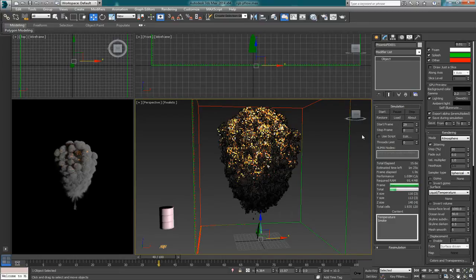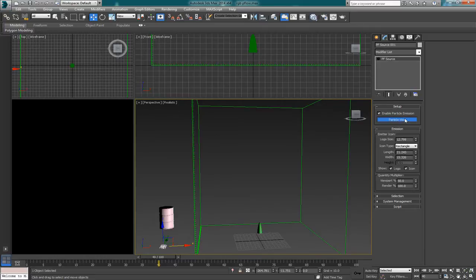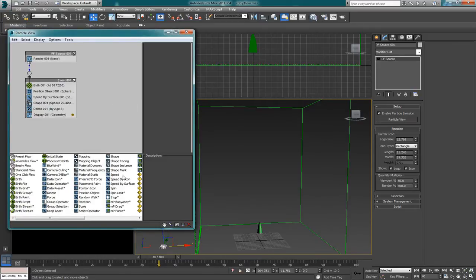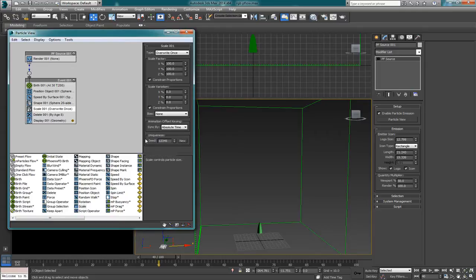So a way to do this is we need to tweak several parameters, and first I will animate the size of the particles towards 0. So I will add a scale operator right here, because the size of the particles cannot be animated, so we need to scale them. And I will use the particle age time base, and also use the absolute type of scale.